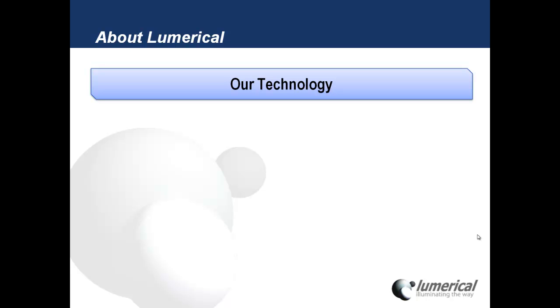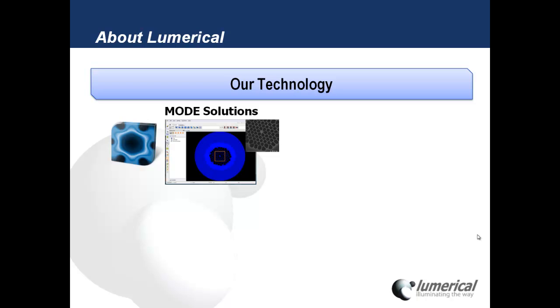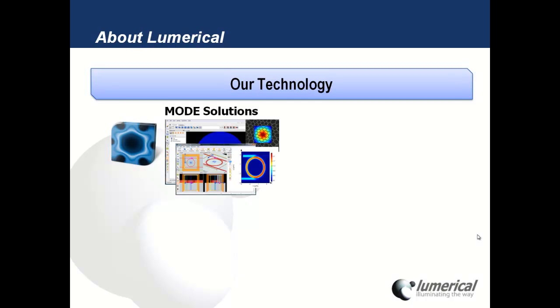So about Lumerical and our technology. We have four products. The first one I want to talk about is Mode Solutions. Mode Solutions has an eigenmode solver which can solve for waveguides and fibers of arbitrary cross-section, like this photonic crystal fiber. And since Mode Solutions 5.0, we've also added an omnidirectional propagator, a 2.5D propagator, which allows for omnidirectional propagation within a plane. And it's ideally suited for silicon photonics or integrated optical problems. It can solve things like this ring resonator very quickly and efficiently. And as we're going to see in the webinar today, we're actually going to use this to design a portion of the grating coupler.